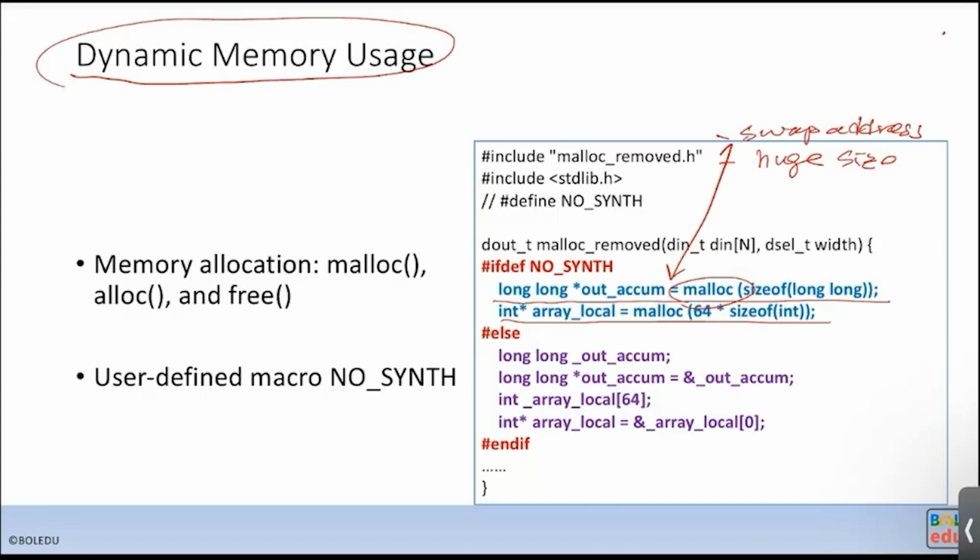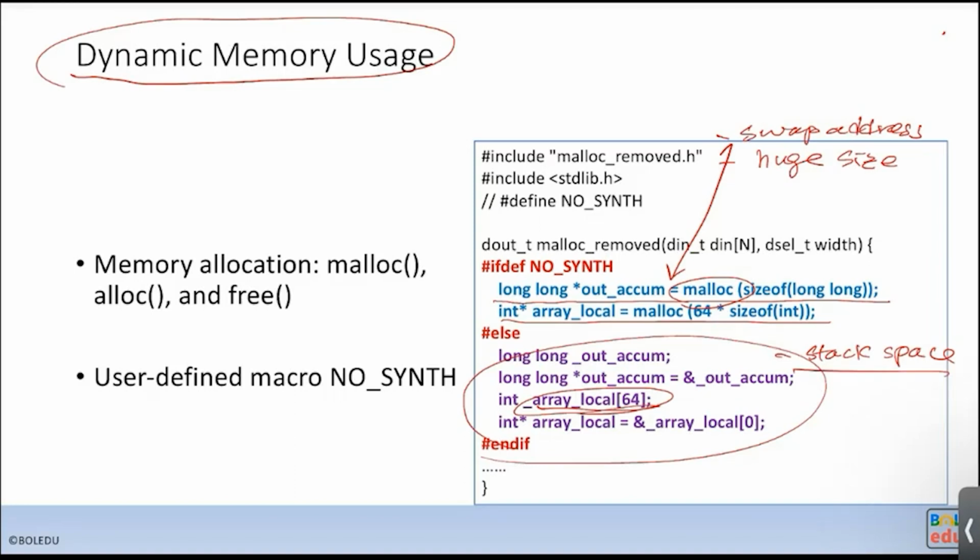You don't want to be limited by, for example, the way you allocate static memory size, and this memory will be allocated in the stack space. And the stack space is quite limited. That's allocated per process. And that will limit how much data size you can run the verifications. But in HLS, you do need static memory allocation, to allocate the static memory size.